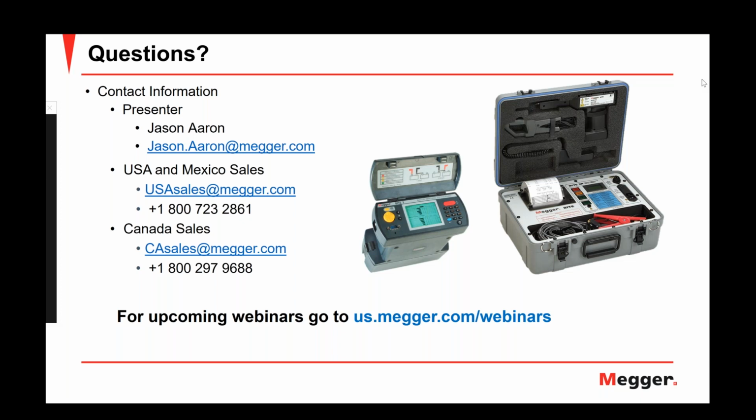All right, thanks, Jason. Sanket, for strap resistance and battery impedance, is it required to have the 72 hours float / no water added? Yes. The reason that is necessary is because we want the cells to be in the fully charged state.